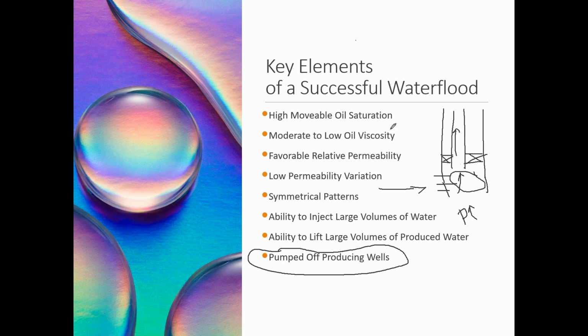So in such cases, if the PI of the well, the productivity index of the well, is high, you might end up deploying an ESP pump basically. You have to incorporate a pump so that this particular fluid can be lifted. Otherwise, the high density fluid inside this wellbore will exert a back pressure, and this will prevent the fluid from moving in this part. So if you create a vacuum or drawdown in this particular area, this fluid will be lifted easily.